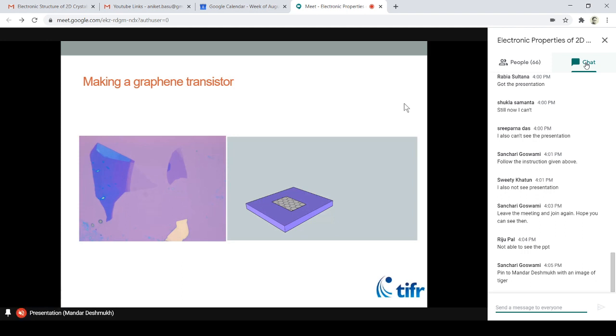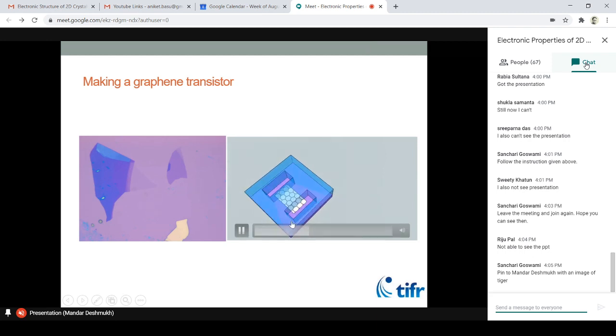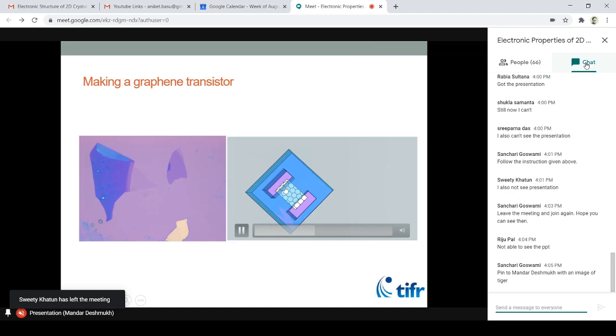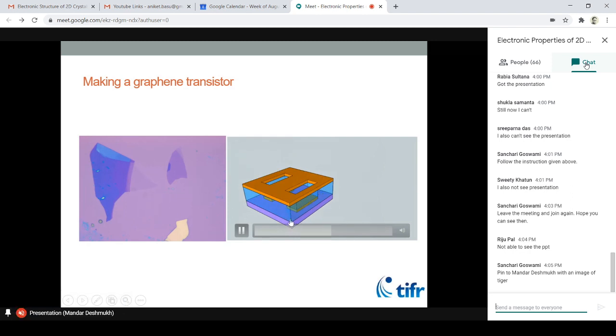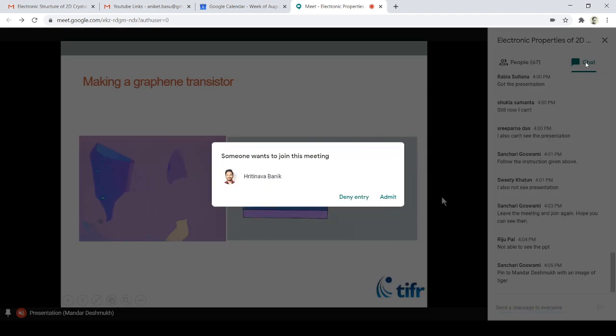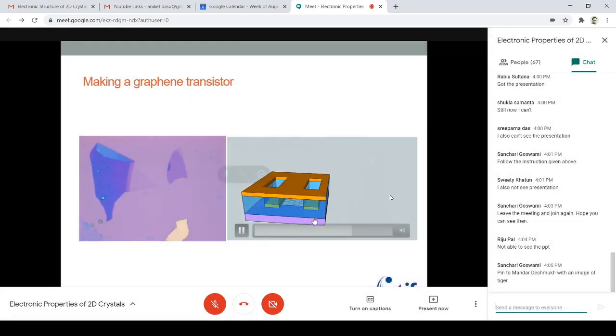And so the process simply works by putting some plastic, essentially a copolymer, on top and exposing it to a beam of electrons or photons, and that kind of changes the property. It actually doesn't remove it, but it changes the properties, and it can be removed by using a liquid. And then once you have it, you can deposit metal on graphene or whatever else that you like, and the metal goes through.